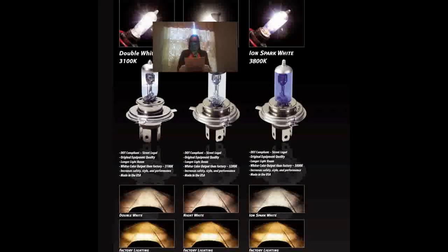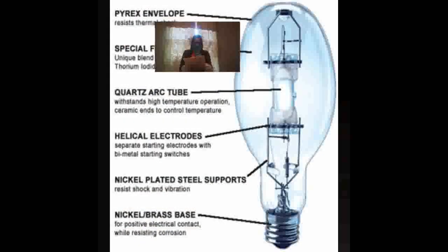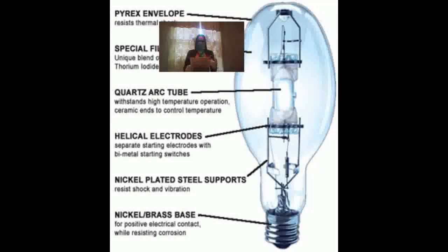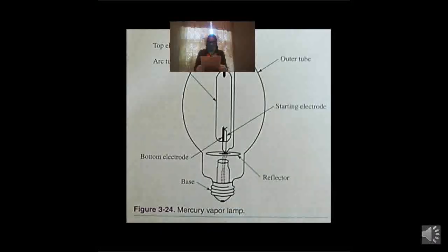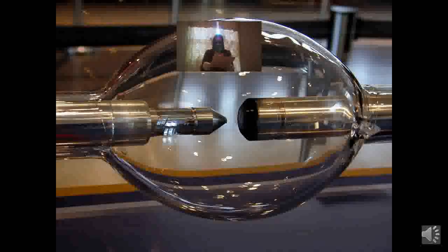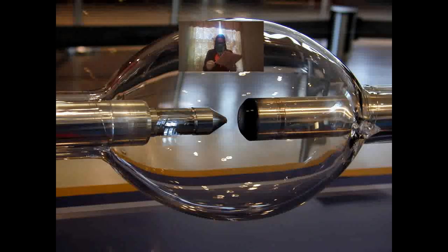The discharge lamp operates differently from an incandescent lamp. The discharge lamp produces light by energizing a gas such as argon, neon, helium, or vapor of mercury or sodium. The gas or vapor is ionized by the electrical pressure and will glow, thus emitting light. A discharge lamp can easily produce 20 times more light than a conventional filament bulb while using the same type and amount of electrical energy. Descriptions of several types of discharge lamps follow.